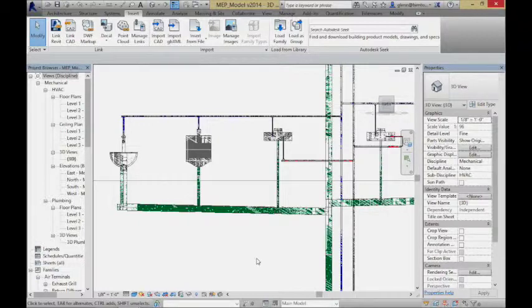Okay. All these things won't drain individually down to a sewer system or out of the building. What we tend to do is tie them all together with what would be called a lateral that's coming across, and then it goes ultimately to a riser that connects things up and down throughout the entire building. So just different terms of terminology.